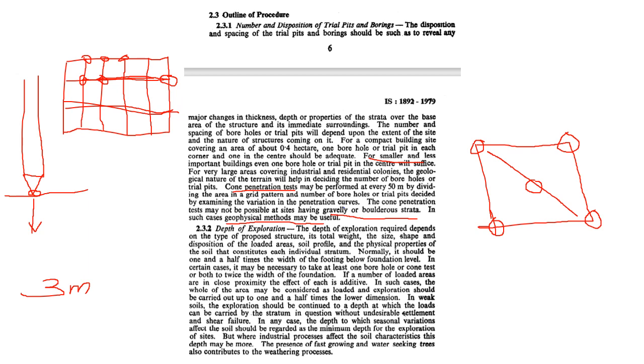So in order to ensure that this is not a big rock or a big boulder, and this is a complete rock system that is existing at the bottom, you have to dig further 3 meters, you have to do the boring further 3 meters into that rock, okay. Then if you are still finding rock, then it's okay, then you are safe with your borehole, okay. So that is how normally you should be doing, or ideally you should be doing.